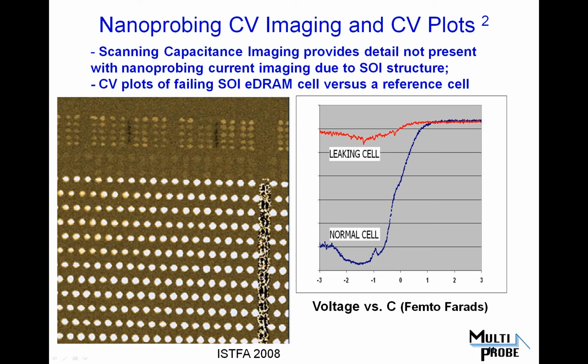This is an important characteristic because on embedded DRAM, leakage of the trench capacitor will affect the ability of the cell to retain state and won't function properly if there's appreciable leakage between adjacent embedded DRAM cells itself. So this is an example of where you can practically measure and apply it and localize a specific leakage between 2 embedded DRAM cells.